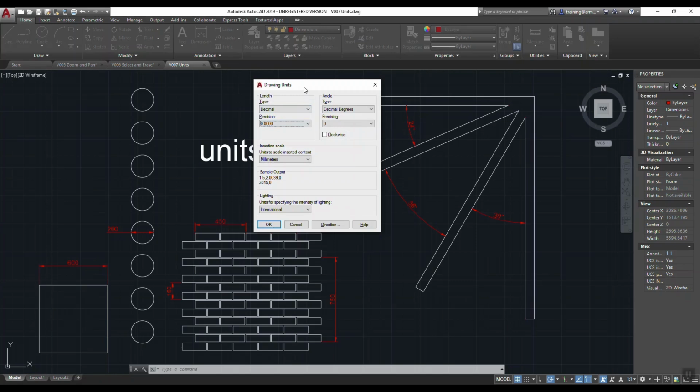But what I'm going to suggest is this. What you need to do is you need to decide on the precision that you want and then add 2 decimal places to it and then choose that. So for instance, on a building site, I might say, half a millimeter is plenty enough. So if I said my piece of wood was 12.5 millimeters thick, that's as far as I need to go with my timber sizes, and I can say that I've got 1 decimal place. But for a building site, here I would argue that you need to change this to 3 decimal places.